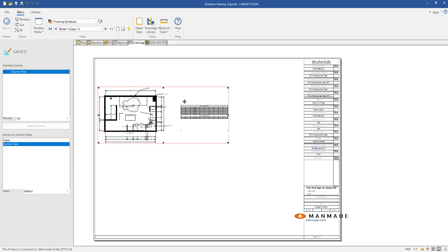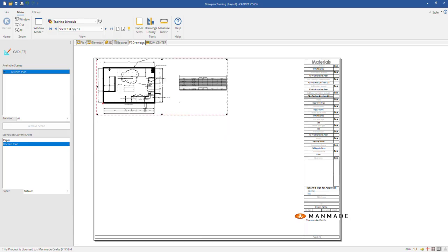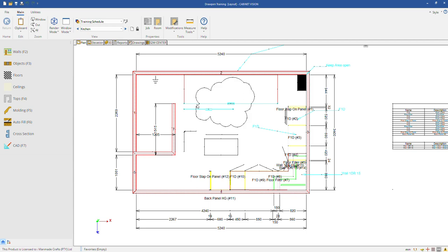So you can then go and get all your images and place them here. You can send it through from pretty much any view that you are in: CAD and Vision, your plan view, elevation view, 3D view, inside a unit, or on your part views. No matter where it is, you can right click to drawing. The basic to drawing sends you through a standard 2D drawing image, and the information that gets sent through with it gets controlled by layers as well.